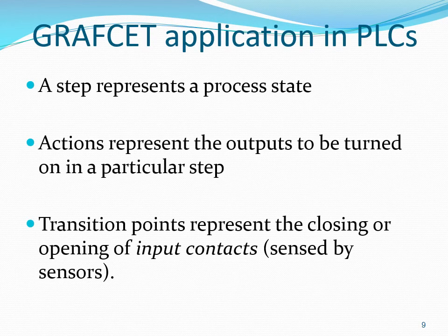When GRAFCETs are applied in the design of PLC programs, a step represents a process state. Actions represent the outputs to be turned on in a particular step. Transition points represent the closing or opening of input contacts. In other words, they represent the states of the sensors.